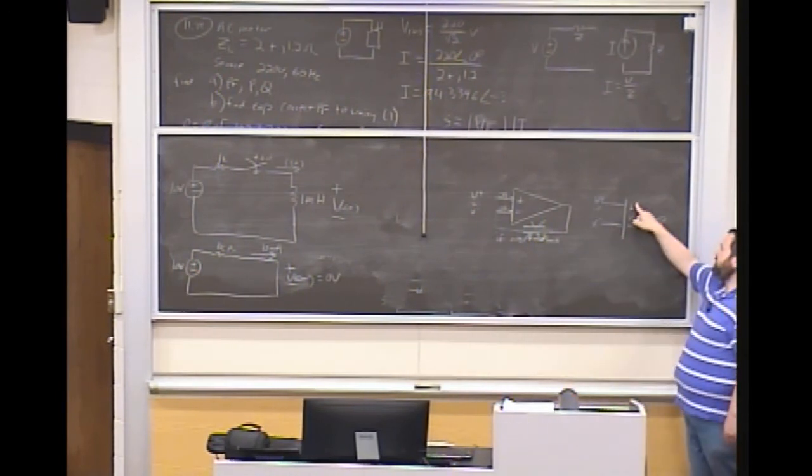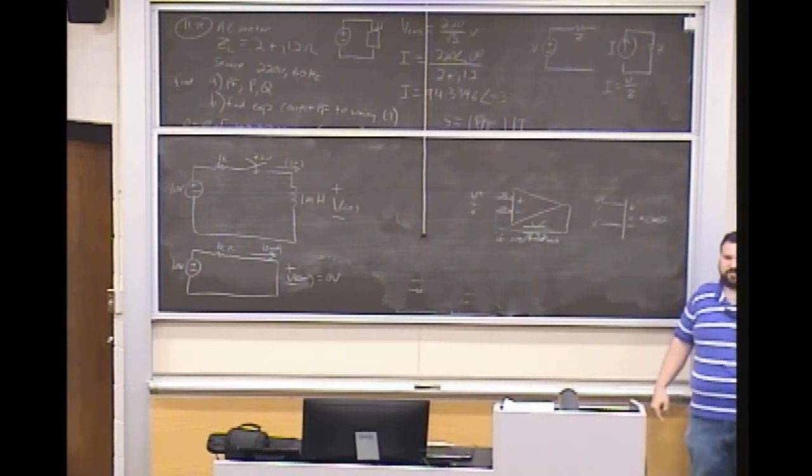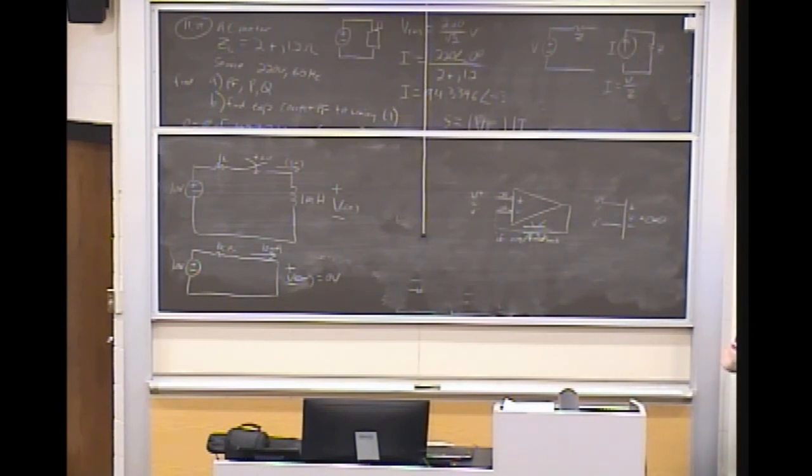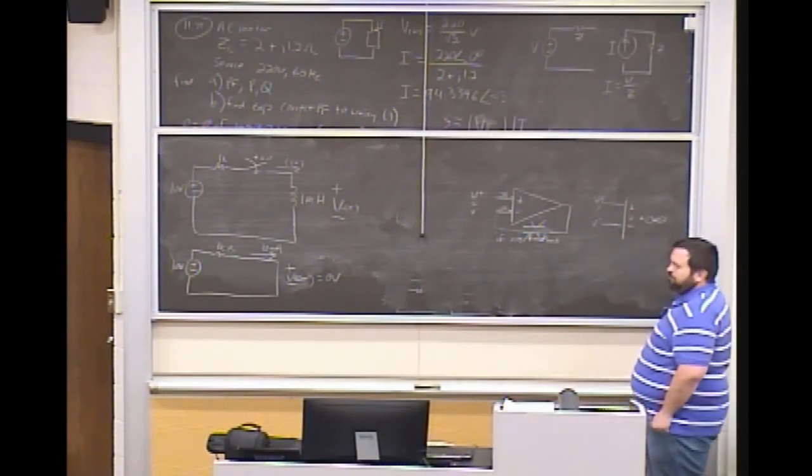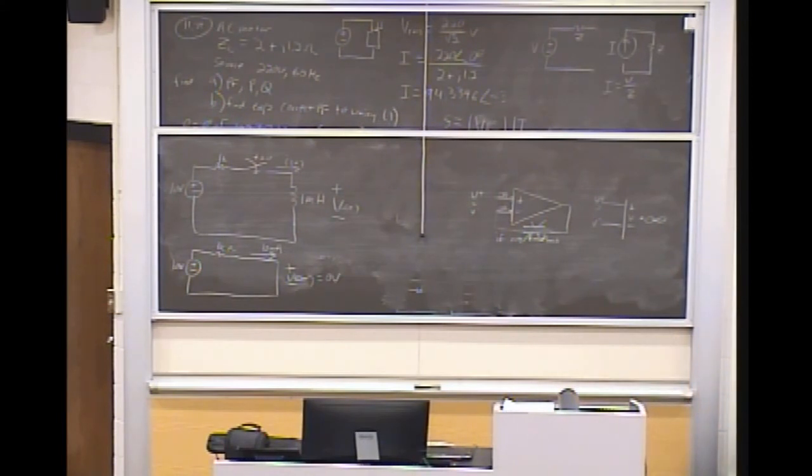If this voltage is bigger than that voltage, that multiplication will almost assuredly be bigger than your positive voltage rail. And if this is greater than that, you're multiplying a negative voltage by infinity, and that most assuredly will be lower than your negative voltage rail.